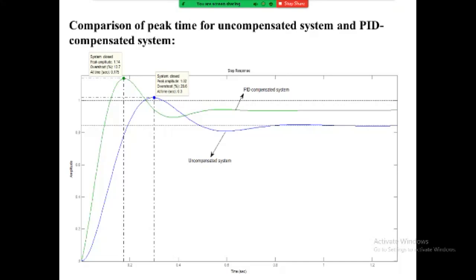From this figure, it is evident that the uncompensated system has a steady state error of 1 minus 0.843, and the PD compensator system has 0.07, and thus the PD compensator system also improves the steady state error. Even though the PD compensated system reduces the steady state error over the uncompensated system, the given requirement is zero steady state error.